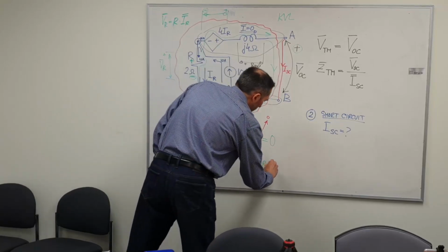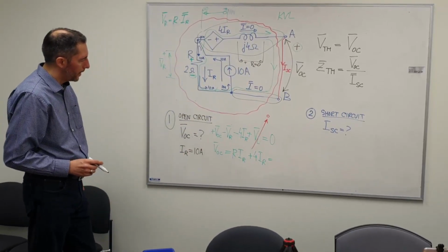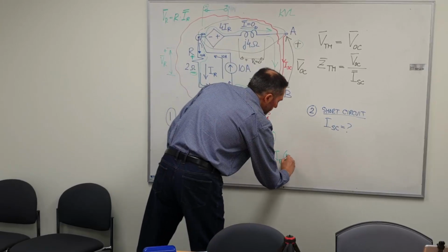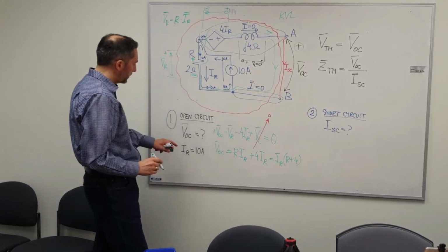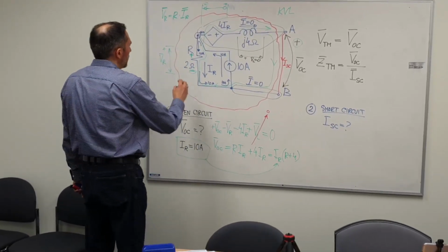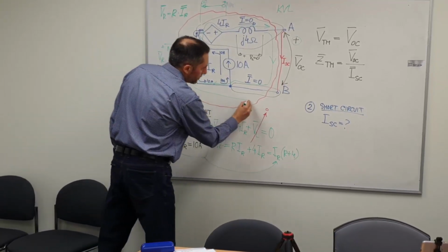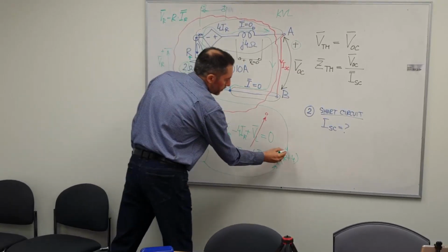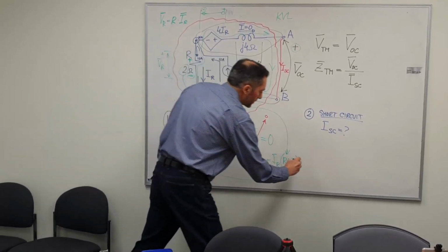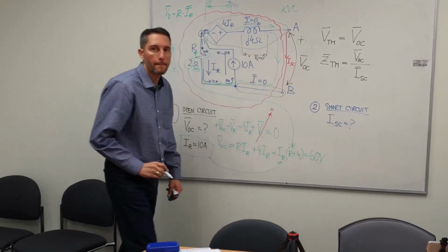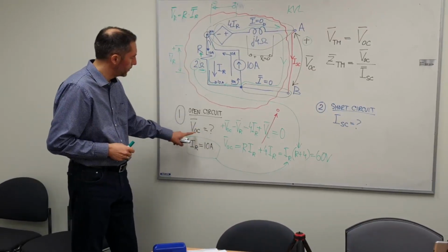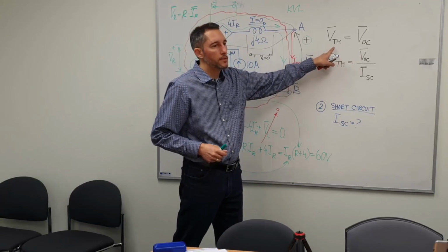So IR, I can probably plug in the values right now, but I can also do something like this. So IR, and then I have R plus 4. Now IR, I already calculated here, that's 10 amps. So 10 amps goes into this equation. Resistance is 2 ohms. That's my resistance here. So I know that 2 ohms plus 4 ohms, that's 6 ohms. 6 ohms times 10 amps is 60 volts. Okay? So 60 volts is VOC, so I have calculated that, and VOC is my Thevenin equivalent voltage.